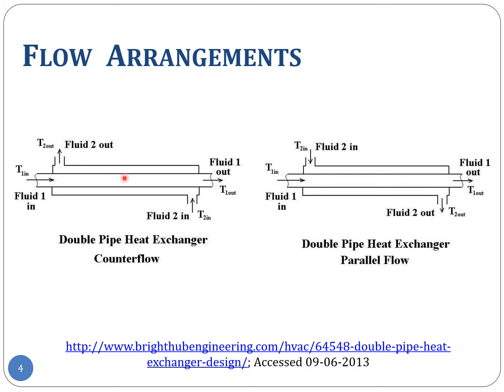So that's the difference. But at any cross section z, the equation shouldn't be different at all for a counter flow versus a parallel flow, because the hot fluid is at a certain temperature, the cold fluid is at a certain temperature. The wall, the inner pipe solid face, is at a certain temperature, or over a range of temperatures basically.